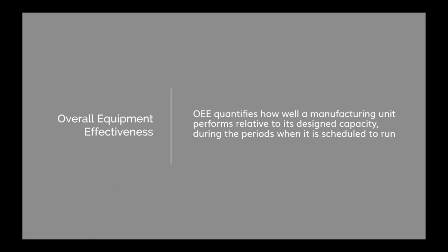Then there is the topic of design capacity. This could be intended as the theoretical speed, that is, for example, the speed the vendor of the machine is declaring as the maximum speed of the machine. But in some industries, for example, in pharma, it is often the qualified speed. That is the speed at which the machine has been qualified to work in normal production.